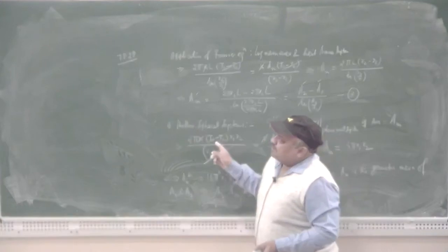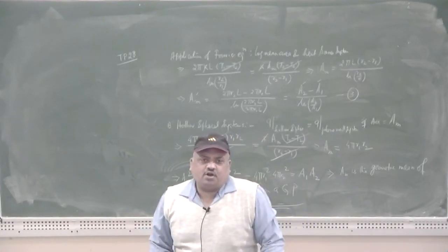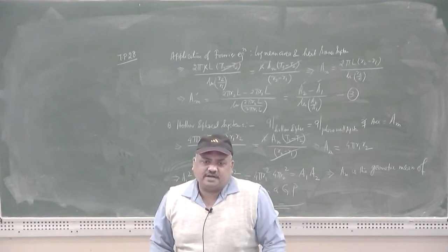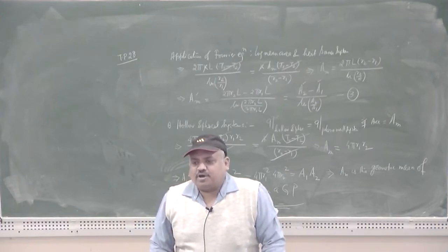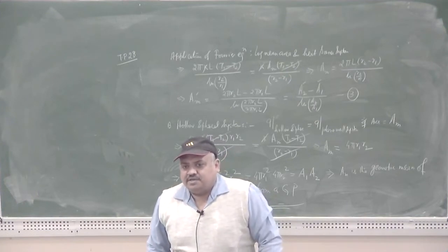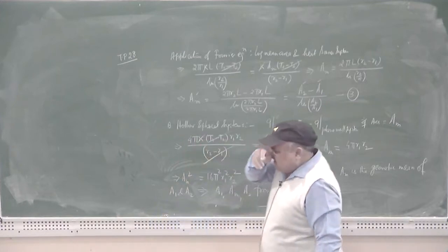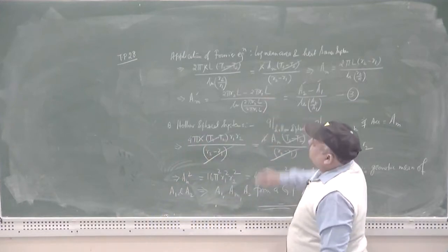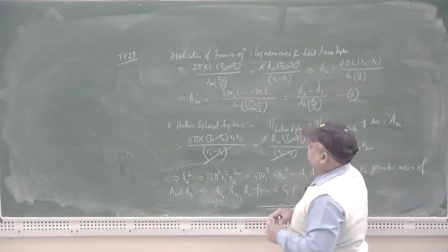It is my request to all of you to go through the numerical problem related with the log mean area in different geometrical conditions. This is of immense importance for the practicing engineer, that wherever and whenever you have to convert a radial system into the plane wall system, the area which should be utilized is the log mean area. So, it is an important design parameter for a design engineer.